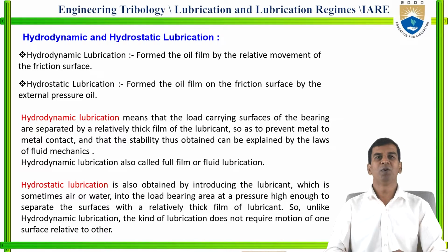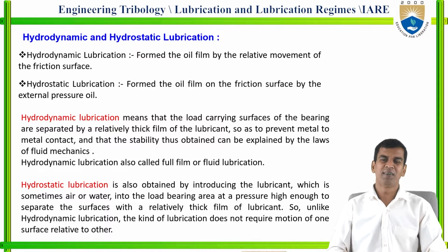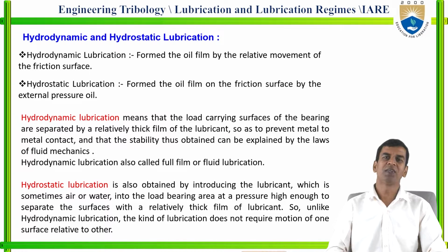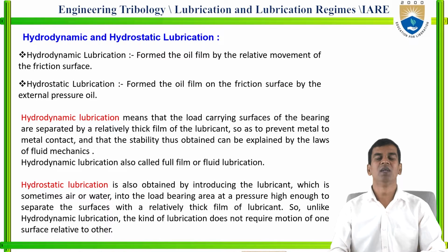In simple terms, in hydrodynamic lubrication, the oil film is formed by the relative motion of the parts, whereas in hydrostatic lubrication, the oil film is formed by the application of a pressurized fluid between the surfaces. These are the major differences between hydrodynamic and hydrostatic lubrication.